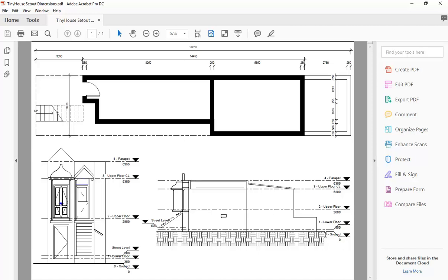Later you'll see when you start to work from surveys, you'll work with an Australian height datum, or level, from sea level pretty much, which is going to be higher than that. But it's fine to reduce it, in other words, to make it a reduced level where we're going to say this is our 0, and everything's going to be measured from there. So just remember that, and then if your floor level is flush with the ground, it'll be 0 as well, but you might raise it slightly to have a step up from the ground, and then it might be 100 or 150, something like that.